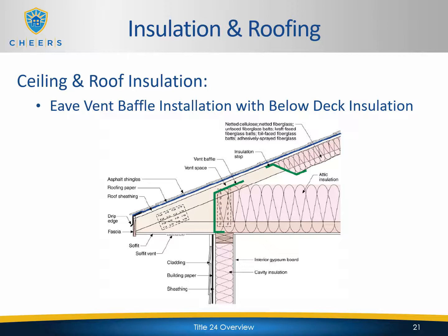But we do need to have these baffles to keep that air from moving through that insulation and reducing the overall effective R value of that insulation.